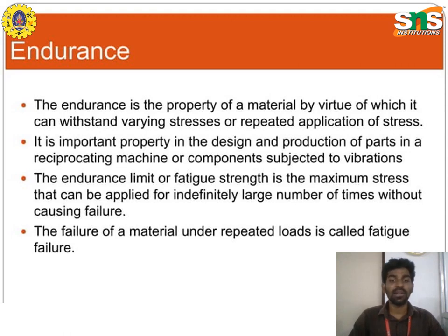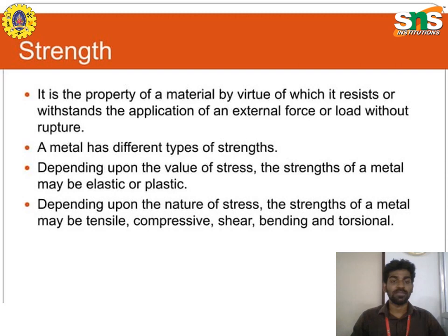The failure of a material under repeated loads is called fatigue failure, and the related property is endurance. It is the property of a material by virtue of which it can withstand varying stresses or repeated applications of stress. It is an important property in the design and production of parts in reciprocating machines or components subjected to vibrations. Strength is the property by which a material resists or withstands the application of an external force or load without rupture, and it depends upon the value of stress.